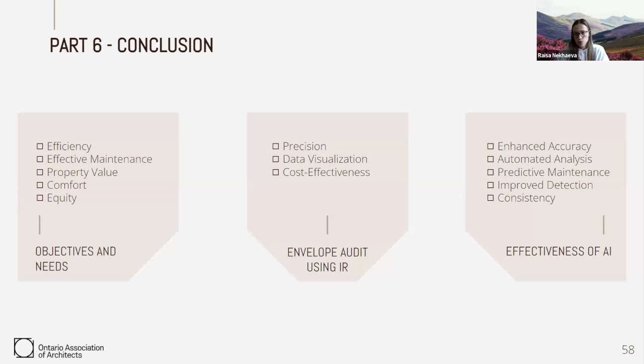And then it also helps us with cost effectiveness. It helps prioritize repairs and avoid costly future issues, and infrared thermography is a non-destructive inspection method. So it does not require us to go and poke holes inside of the building.